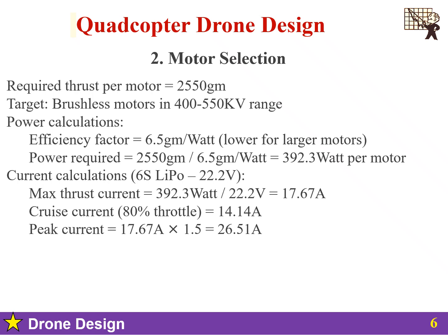Notice our efficiency factor has decreased further to 6.5 grams per watt. This continuing decline in efficiency as we scale up reflects fundamental physics. First, larger motors have increased electromagnetic losses. Second, higher power densities generate more heat. Third, mechanical losses scale unfavorably with size. Fourth, larger air gaps in magnetic circuits reduce efficiency.